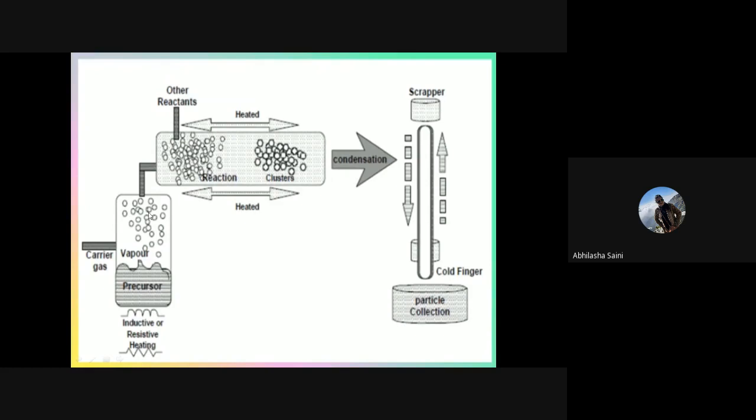So this vapor of the precursor is going to go onto that substrate material and sit on top of it. These vapors will sit on the substrate material, and now they will react. The reaction of this precursor vapor will take place on that substrate material, at high temperature and pressure. Here the reaction will take place on the substrate itself. Clear guys?